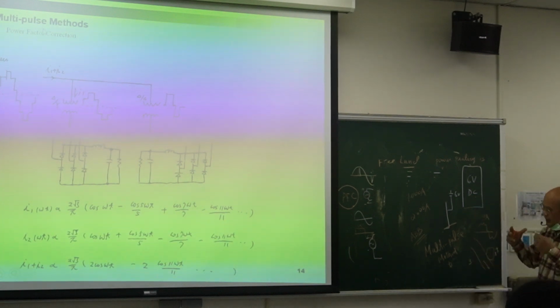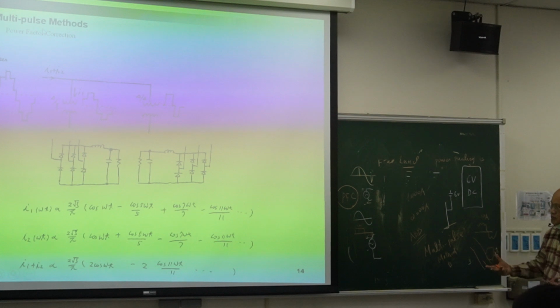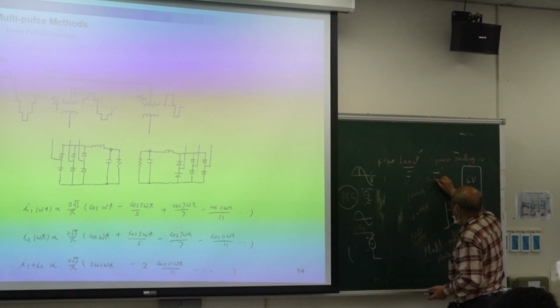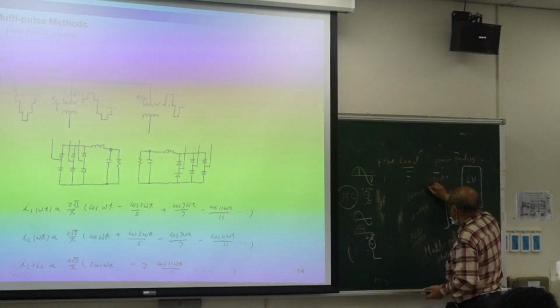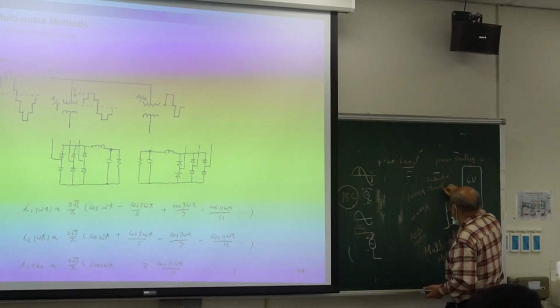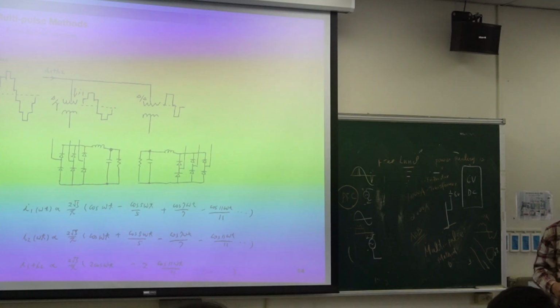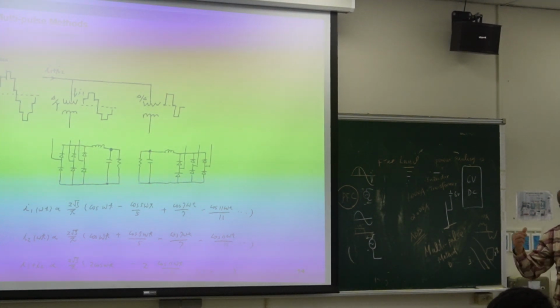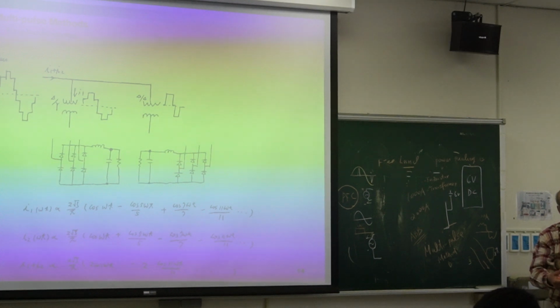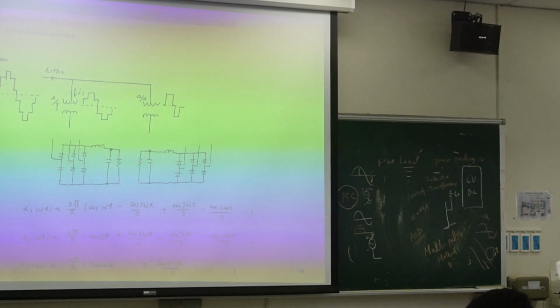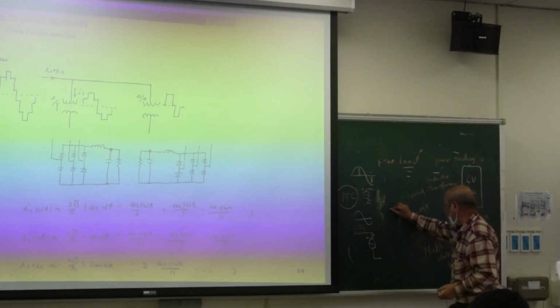They say we cannot use devices. We have to use another way. What can we use? We can use an inductor. We can use a transformer. So they use an inductor. They use a transformer. Do you think an inductor or transformer is passive or active? What is an active device? Switch, active, right? But how about an inductor? Passive. So they call this passive PFC.